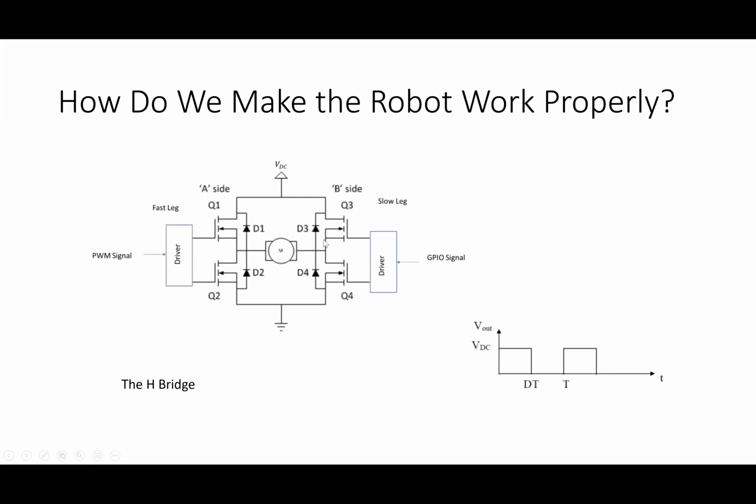was this thing here called an H bridge. I skipped over it. But if you've ever built a motor or done anything like that, if you had a microcontroller driving a motor, usually you have something called an H bridge that connects between the microcontroller and the motor. And what you do is you apply a voltage to the motor that looks like this. It basically goes up to a particular value, then goes down, then goes up to a particular value, then goes down. It just repeats like that. What kind of wave is that? Anybody know?